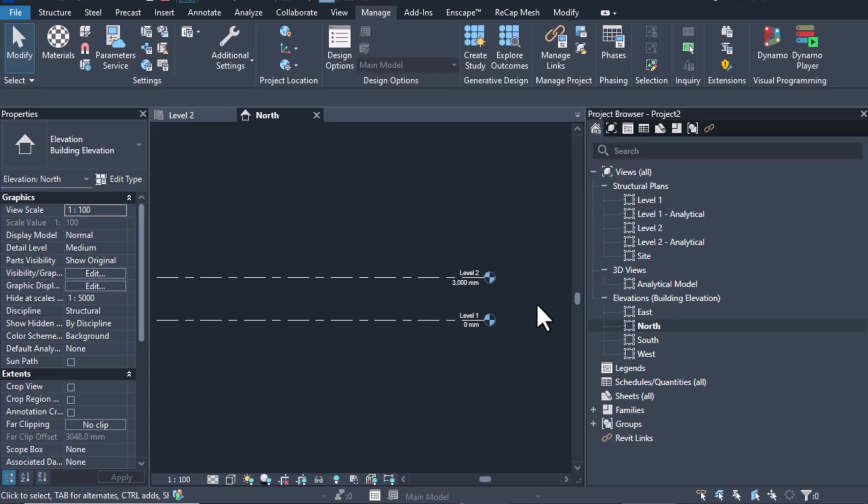It can show the top of structure, the top of beam, the top of slab, the top of foundation, the splicing of the columns, and there are various other depictions that levels can do within the elevation of a structural model. Also, the levels can be of the foundation, of the basement, and of the various subgrade levels that they can depict in a model.